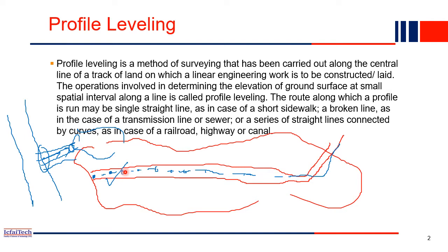And also sometimes if you construct a road, sometimes we need to cut the hill, and sometimes we need to fill the valley also. So profile leveling basically helps us in identifying how much earth cutting is required, and earth filling is also required.